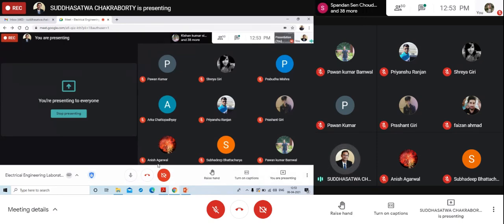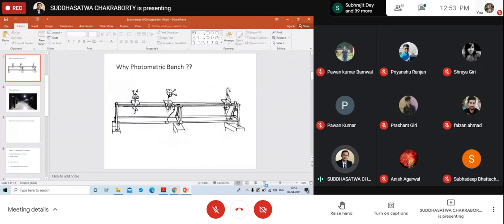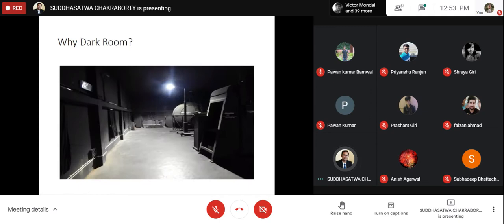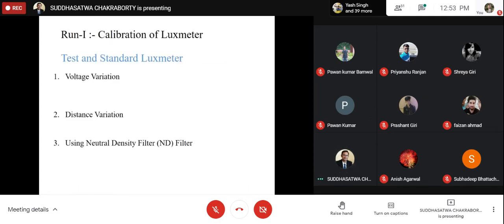So SPD, spectral power distribution, we already have talked about. We already have seen the SPD last day. Now I think we are all accustomed with the term SPD. The SPD has a very interesting relationship with the input voltage. If we start changing the input voltage, the SPD of the source also starts changing, and that change is not linear. That is the disadvantage of this voltage variation technique.